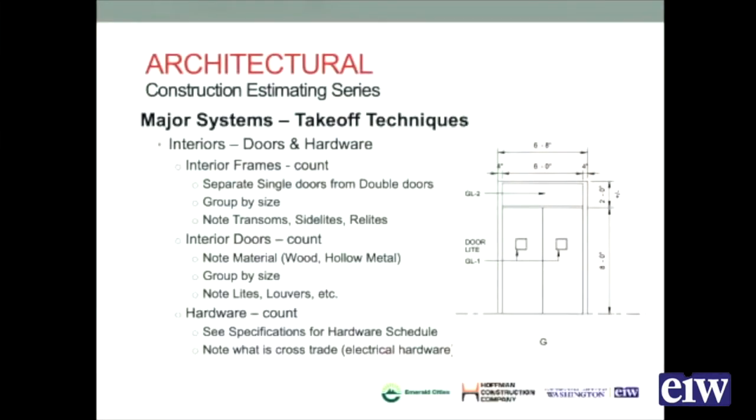Now, as you work through doing the takeoffs, you'll start seeing that you can group the material pricing. For the material pricing, I can group some of these sizes together. It might be, I'm going to summarize all my 3-foot wide to 3'6" wide doors together because there's not much price difference between a 3-foot door opening and a 3'4" door opening. Experience will tell you, as you get the pricing on the material side, what you can group and what you need to break out.